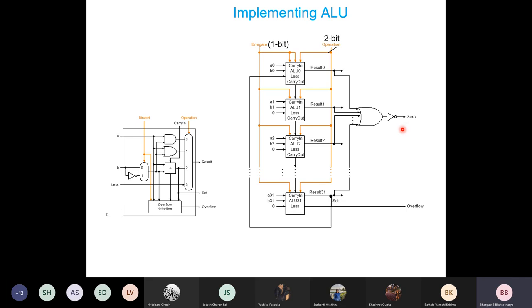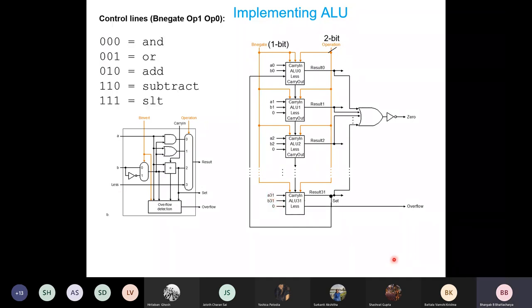And in order to implement set less than, we subtract, and if the less-than condition is satisfied, then the result would be negative, and therefore the most significant bit here should be 1. Then for setting the register, you tap this signal to set the least significant bit of some register, which is RD. We set this value to 0 and this value to 1, and all other values are set to 0 here. Look at this third input here. Okay. So I think this is straightforward, and it's not so difficult to understand.